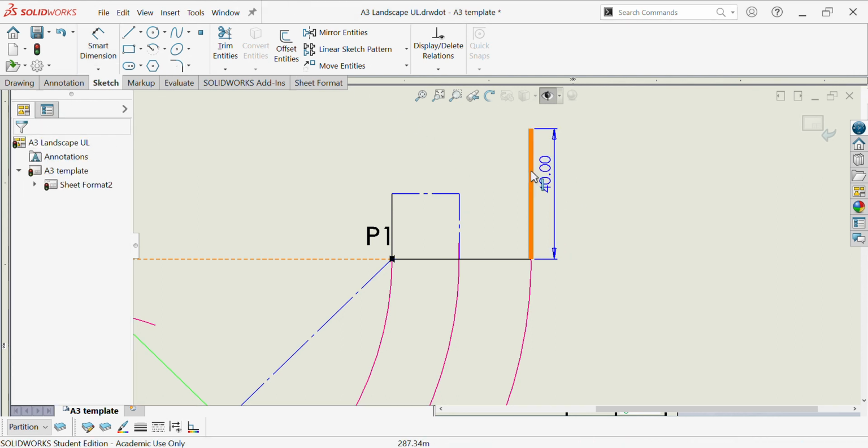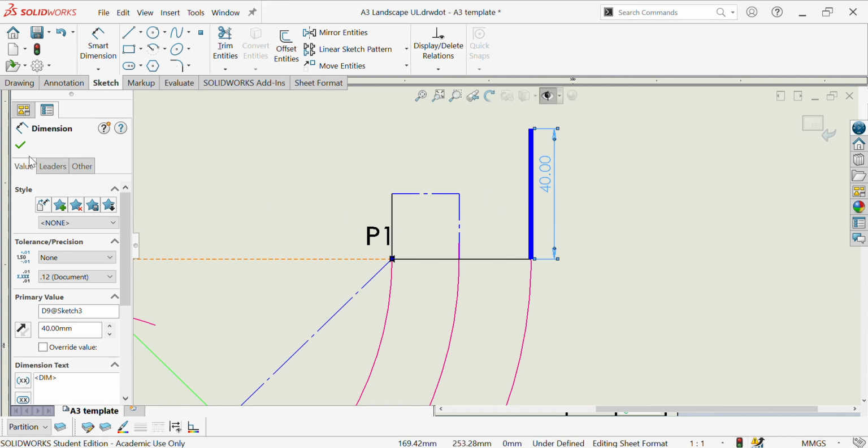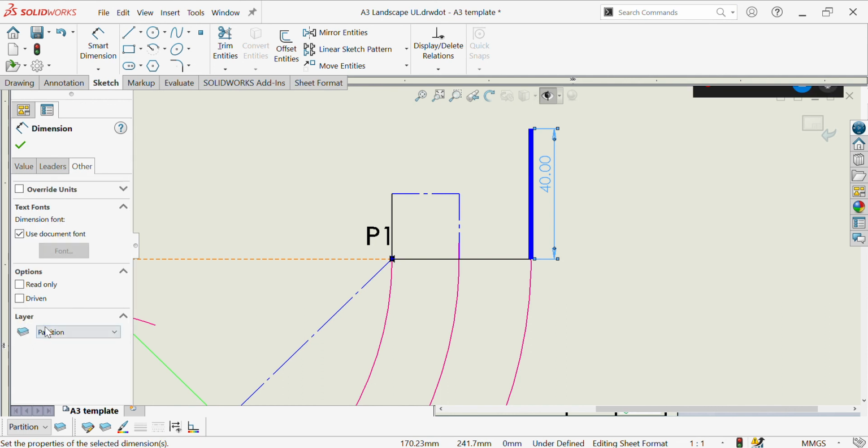That's probably the hardest part, is knowing what orientation it's going to be and where your measurements are going to plan out. But as long as you take your measurements from the original shape and just bring them off the arcs that you've swung up, just obviously making sure that horizontal lines are horizontal and vertical are vertical, they shouldn't run into any bother then. So I'll just make that dimension hidden, just keep it out of the way.